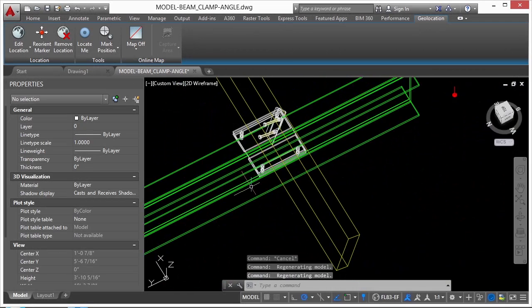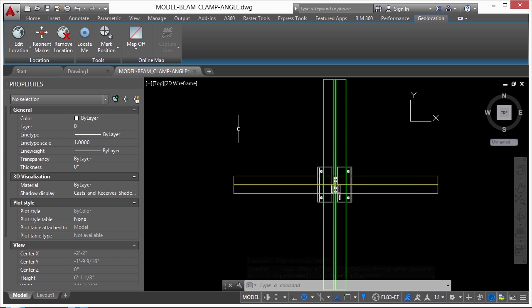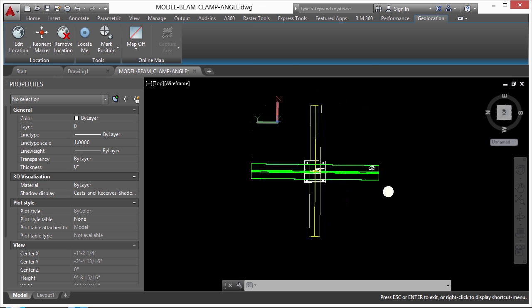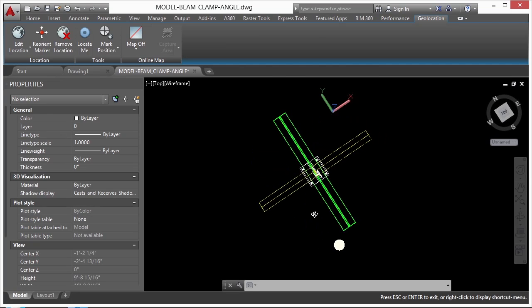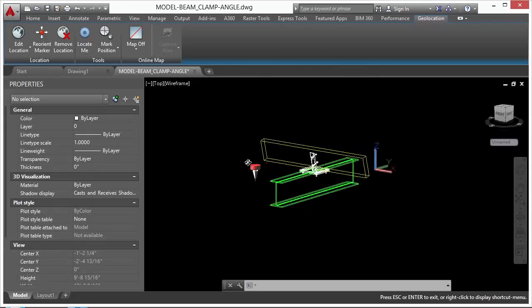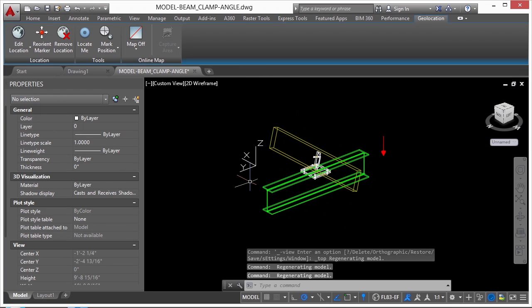Well, let's say I needed to show this in a drawing at a very specific view. Now, I can go to my top view or whatever I need to do in paper space. One thing that I can do, as I just showed you there, is the 3D orbit command. I can get to that in a couple of different ways. My preferred way is what I feel is the simplest. Hold down the Shift key and hold down the middle mouse button. Just press them both at the same time and hold them down and move your mouse left and right. That'll rotate it. And if you move it up and down, it'll rotate it this way. If you do it in conjunction, it'll rotate them in multiple different axes at the same time. And so this is a great way to get a different view of your drawing.